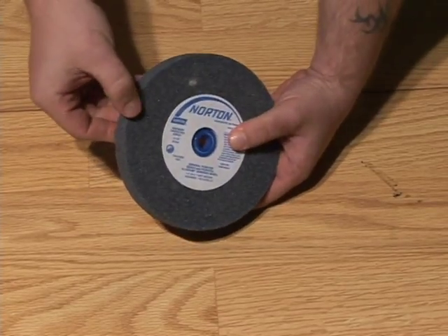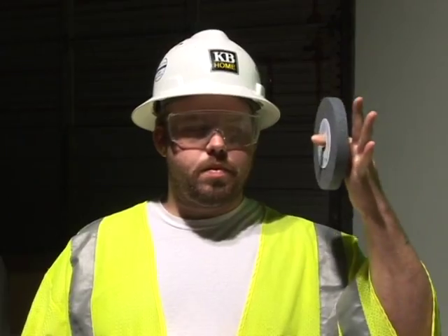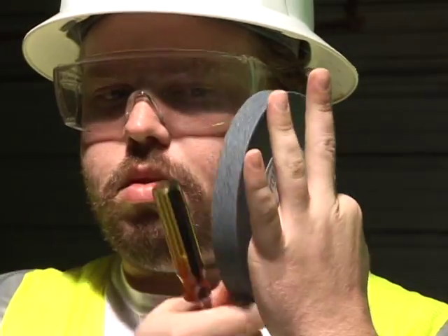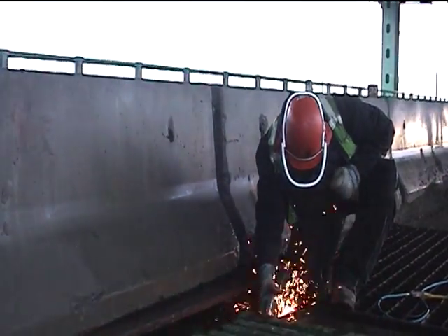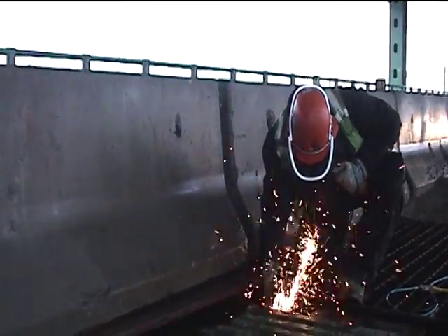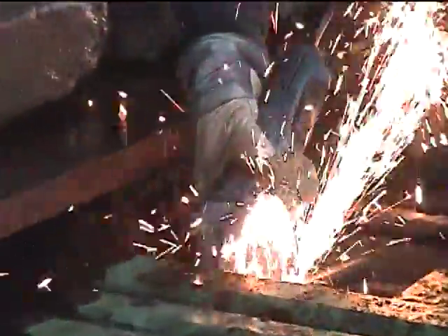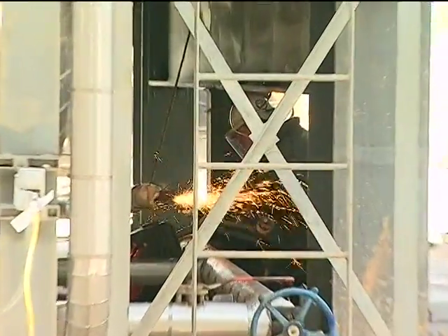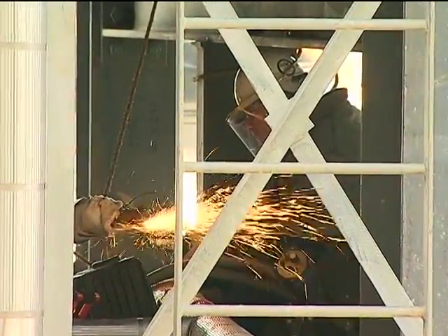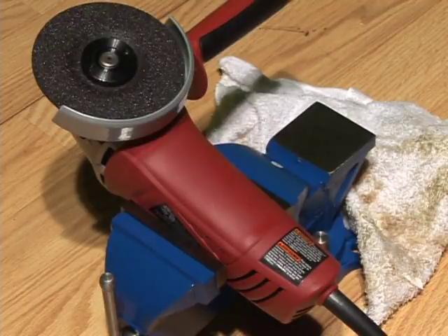Abrasive wheels must be inspected for damage and be sound or ring tested before being mounted. A stable or undamaged wheel will give a clear metallic tone or ring when tested. Abrasive wheels must be equipped with a safety guard to protect workers from the moving wheel surface and also from flying fragments in case of wheel breakage. Never stand in the plane of rotation of the wheel. Always wear eye protection and a face shield. Turn off power supply when not using the tool, and never clamp a handheld grinder in a vise.